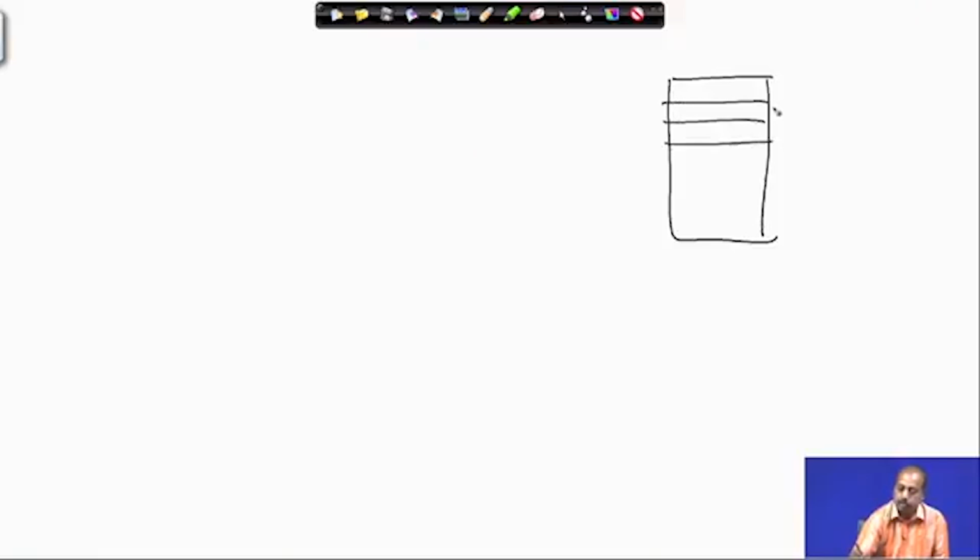So, what we do first is, in the R0 register we move the value 50 hex, because R0 will be used as the index to access this memory location. And there are 10 numbers, and that count we move into the register R5.